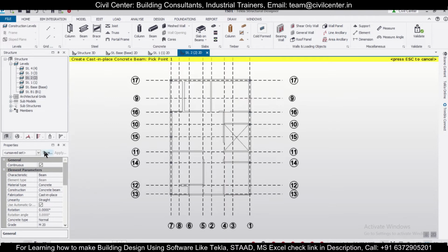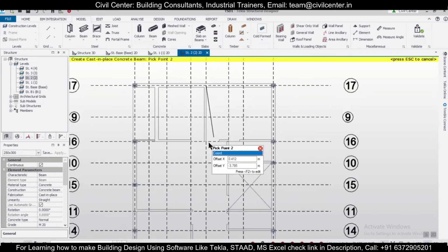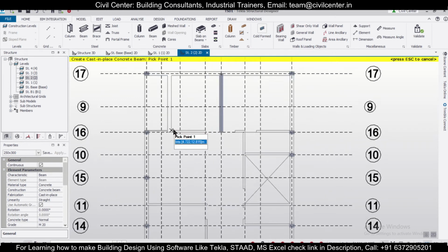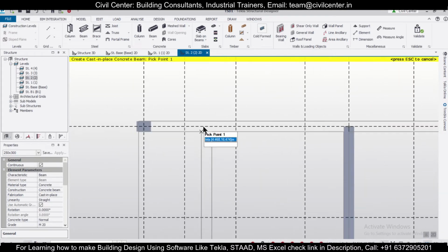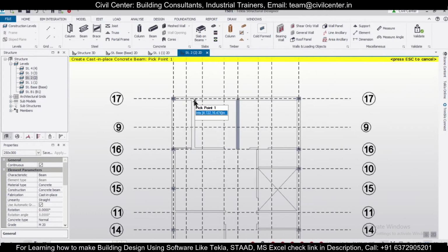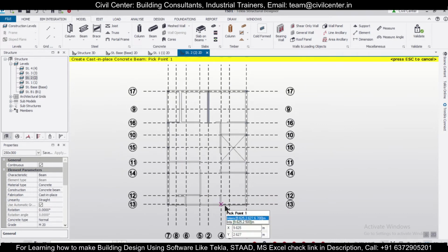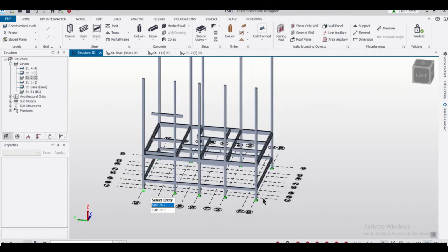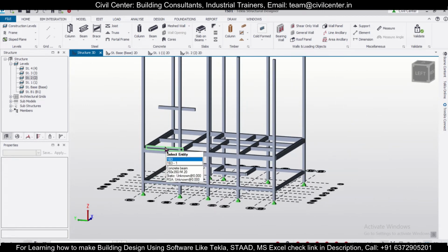this beam will assign beam will take, and first of all let's go with 250 to 300 one, and if there are any internal beams, we can just assign them. This beam will go up to this. This beam should have had a center line. There was some error in omission of this particular beam. So what can we do? We can go back and make that, or else we can also go to the 3D view and just, as you can see, we have this particular level. We can copy this beam later from one level to another, so we'll do that later.